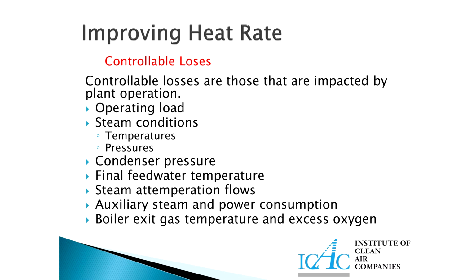The reason the condenser comes into play is because, as I will show you further down, 60% of the energy that you put in gets lost in the condenser. It's a significant amount. Then the feed water temperature, which is the water temperature entering the boiler. The colder the water, the more energy you have to put in.